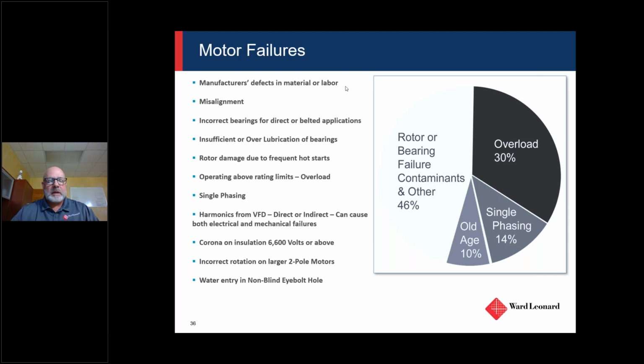One of the things that we see a lot is people using IEEE 841 type motors when an API 661 spec motor is the right one to use. The API spec motor is designed for cooling towers and belt driven loads, right? So that's kind of where those are at. We can help you understand that too, if you want your motor applied correctly.